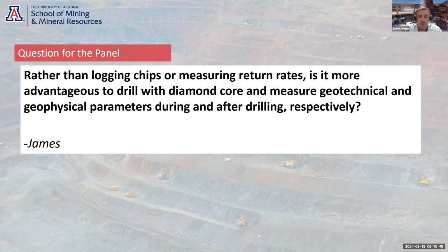There would have been some kind of exploration or resource drilling or geotechnical drilling, which is normally done with diamond core. Get your VWP in there, and then drill your larger diameter well, and then use that VWP to do your hydraulic characterization. So I wouldn't say it replaces, but it's definitely done in parallel in support.